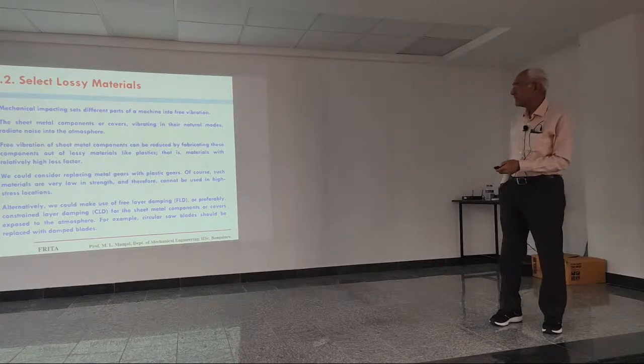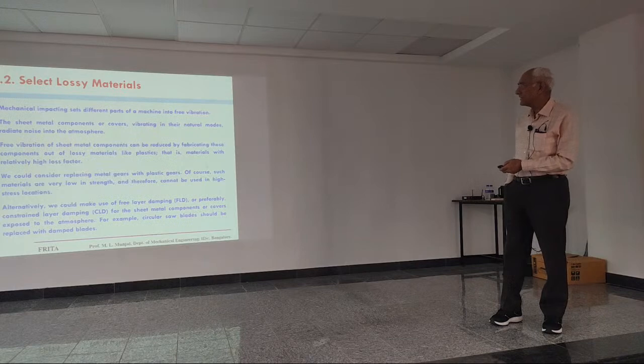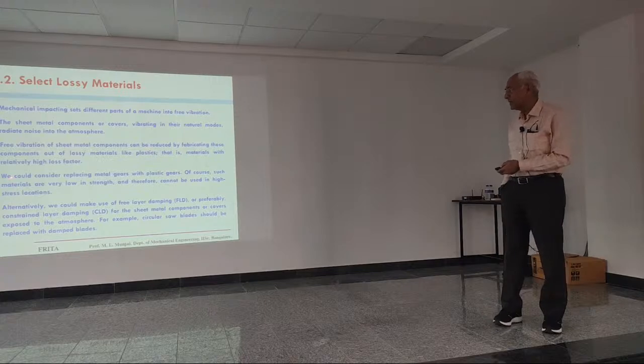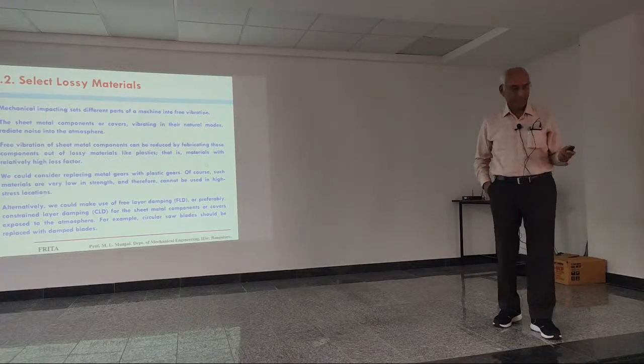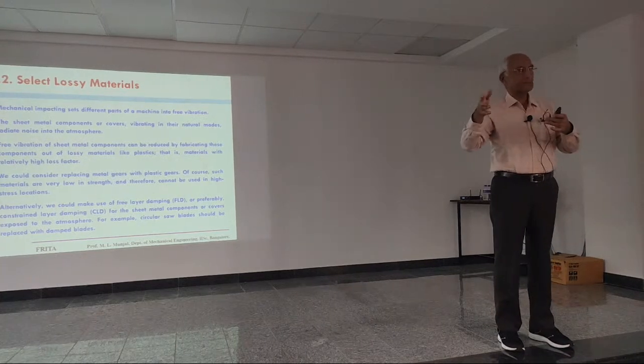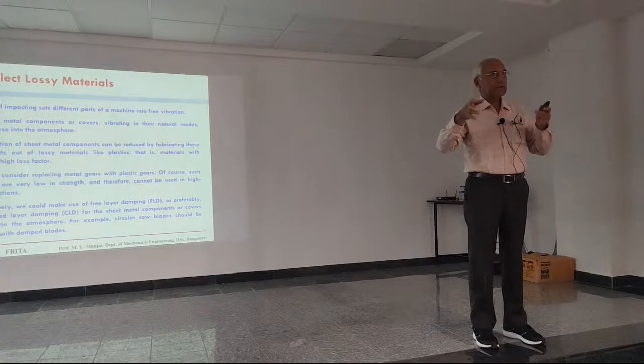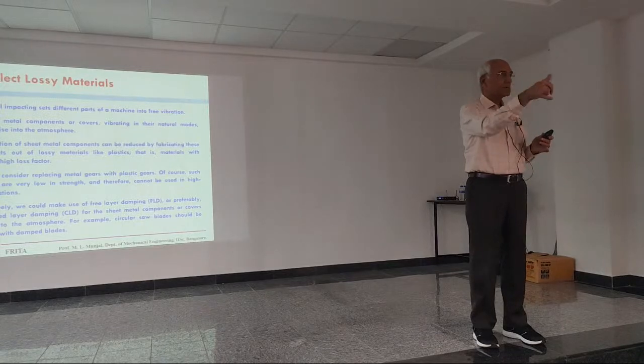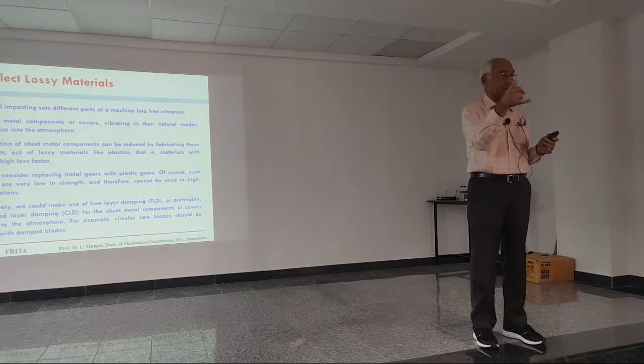Okay, let's see. The free vibration of sheet metal components can be reduced by fabricating these components out of lossy materials like plastics, that is, materials with a relatively high loss factor. Now, all of you know that stress divided by strain is the elastic modulus. But in real practice, elastic modulus is not a real number, it's a complex number.